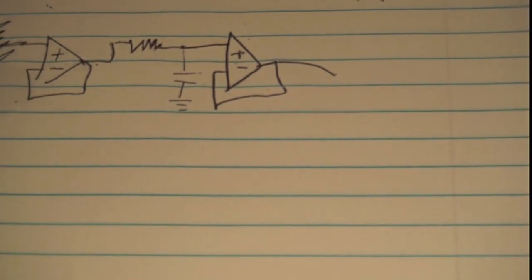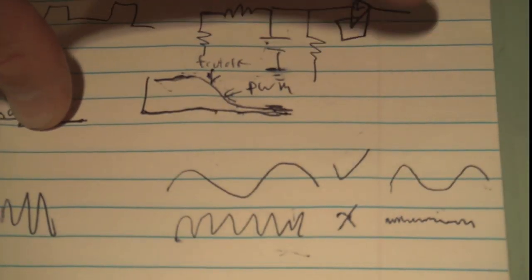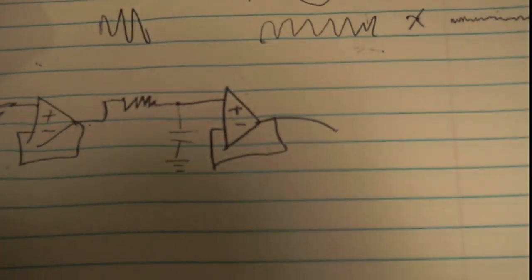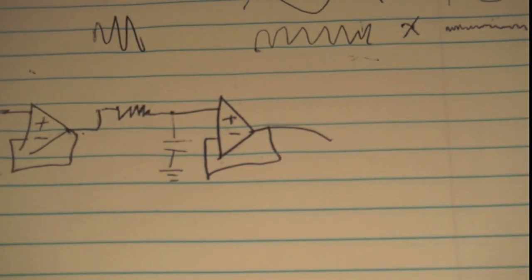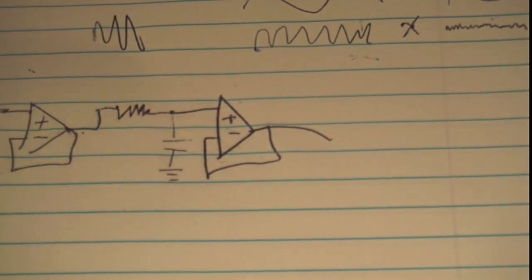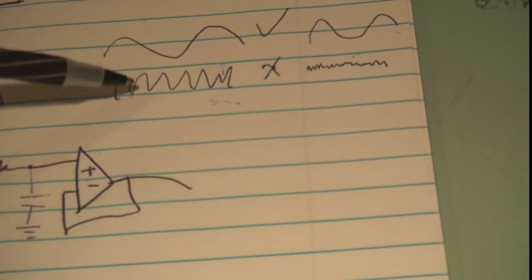This filter is going to keep getting better and better, and we're going to keep making the curve sharper and sharper. You remember this curve up here? We're going to keep making that more like this until we get a smooth analog value out of the PWM. Okay? So also for this filter, I've sort of explained the operation here, but I haven't done a perfect job. Okay? So if you have a super high frequency,